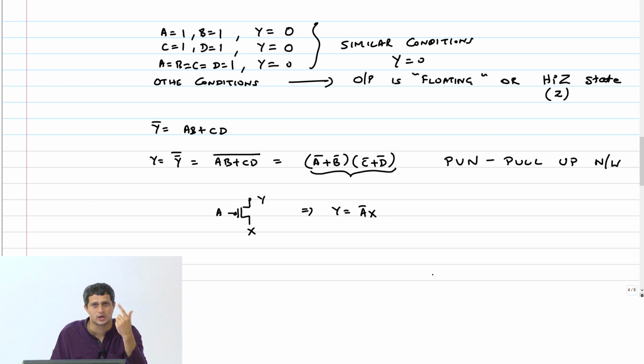The transistor will turn on and thereby conduct, right? And therefore this is an active low switch. So when you see an A bar, you actually just need to connect A to that PMOS transistor. Here, look at this. This one, and this one.